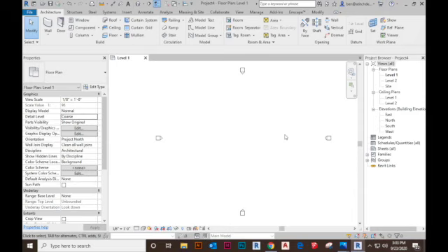There are three ways in the Revit project environment to create a new system family. The first is the duplicate function under your Edit Type tab. The second is to copy and paste a system family from another Revit project. And the third is to transfer project standards from another Revit project under your Manage tab. For this tutorial, we are only going to focus on the duplicate function. So let's draw some walls.